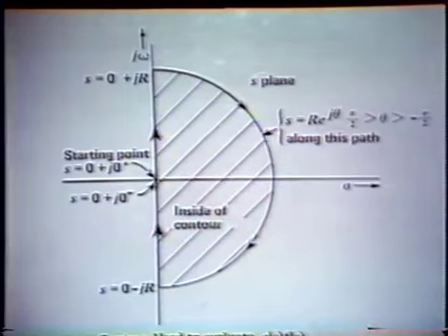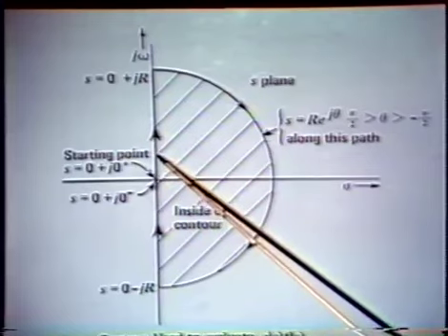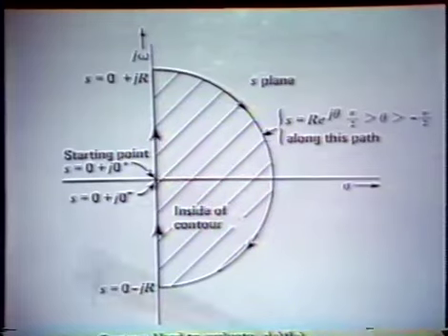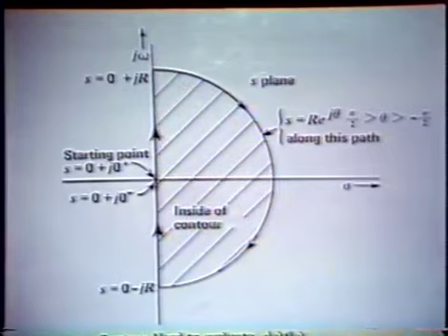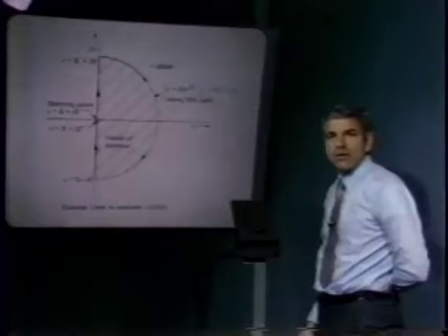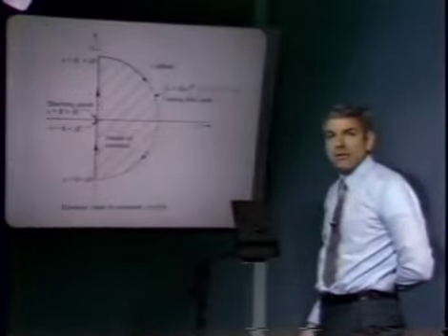We get magnitudes and angles for the AF product corresponding to the values of s along this line. And of course, those are simply the values that we get if we made frequency response measurements, because evaluation of the AF product for s equals j omega is exactly what we get when we evaluate the frequency response or measure the frequency response of our system. So we can get the values of the AF product by experimental measurements. And as I mentioned earlier, that's one of the advantages of the Nyquist test. We can use experimentally determined data in order to look at the stability of a system.